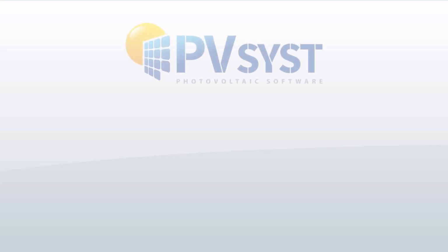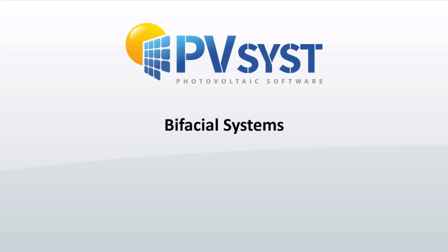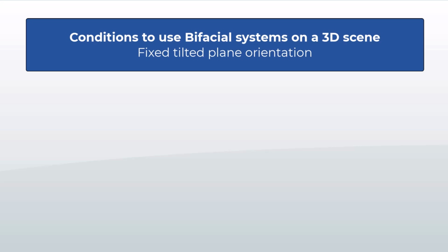In this tutorial, we will show how to simulate a bifacial system in PVsyst. We will explain mandatory conditions for using bifacial panels in a 3D scene. Until now, we have used only orientations, unlimited sheds, and unlimited trackers, but it is also possible to use the bifacial model along with the shading scene.